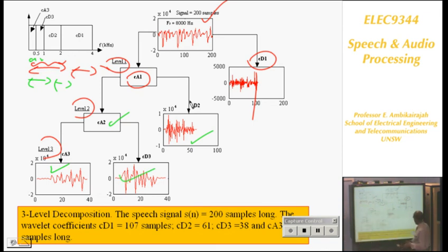Now you can see these are the waveforms that you get on a multi-level. These are all wavelet filters you have. And on these multi-levels, you can actually modify these coefficients. If this is a noisy speech, you can maybe suppress these two signals and then reconstruct them. You may be able to remove some noise. So for noise reduction, we can use wavelets. You decompose the signal using this filter bank technique, and then at various levels you do processing, and then you reconstruct them using the reconstruction I showed you.